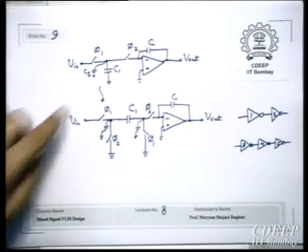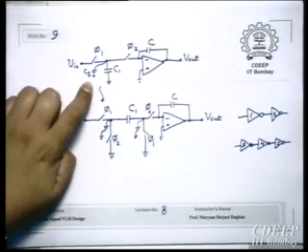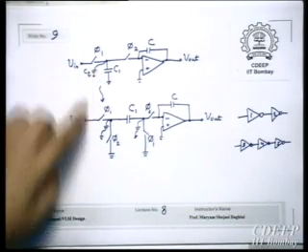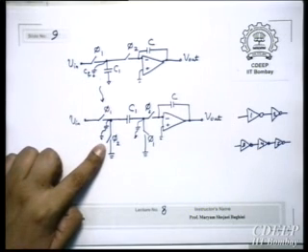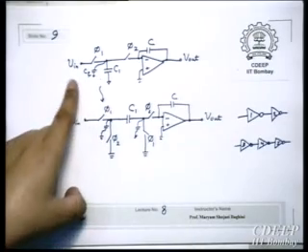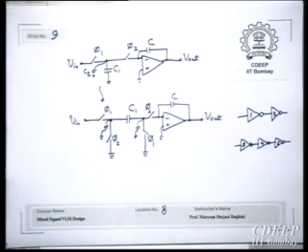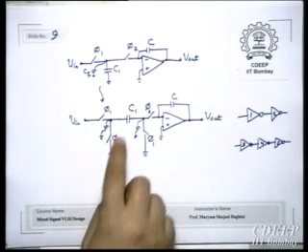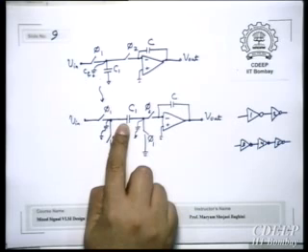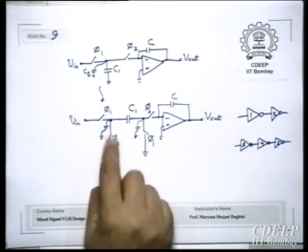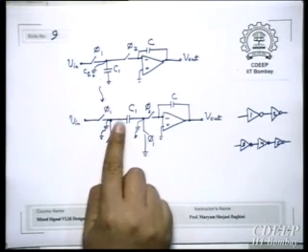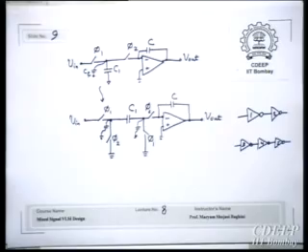Okay, so is it clear? Whatever additional charge we get here will get discharged to the ground. Therefore, no charge which is a function of Vin will be transferred to the output. This essentially means we always keep this left plate at the 0 level. Therefore, the net charge won't change. This is for forward Euler.